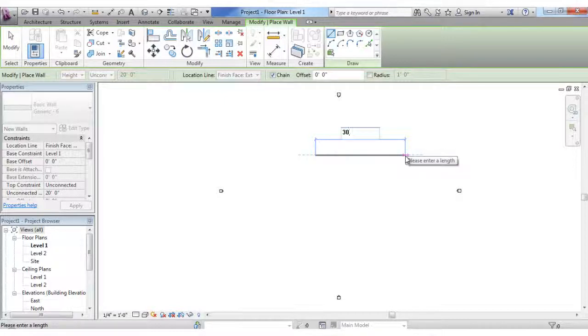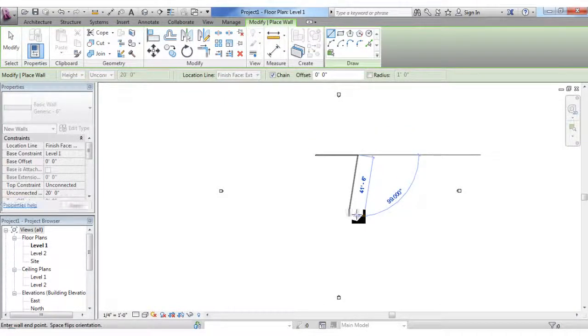So you're going to just type in 30. Revit defaults to feet as opposed to inches, so it's completely opposite in that respect from AutoCAD. Keep that in mind. So 30, just 30, enter. And if I want to add inches, I'm going to pull this down and do 22 feet, 5 inches. Let's make it 6. I'm going to type that in, 22 space 6. I don't have to add any foot mark or anything like that. I'm going to type it in, 22 space bar 6, enter.